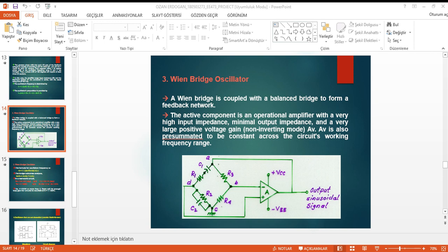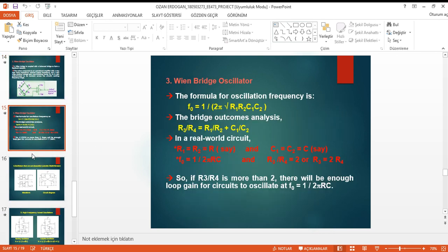boxes. In addition, the oscillation frequency in this kind of circuit can be varied quite easily, as it just needs variation of the capacitors C1 and C2. However, these oscillators require a large number of circuit components and can be operated up to a certain maximum frequency only.